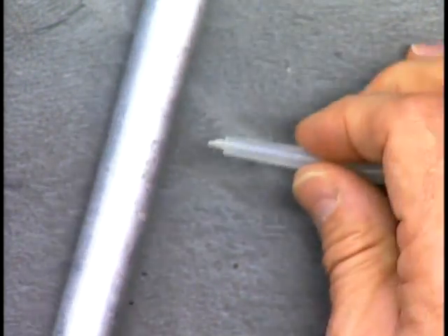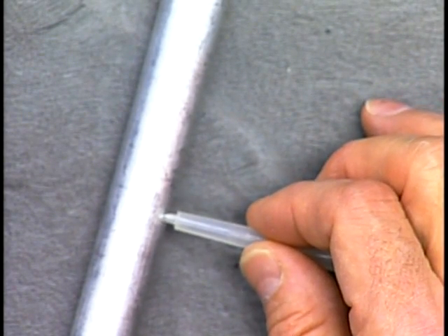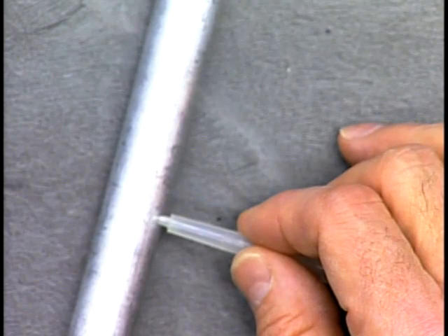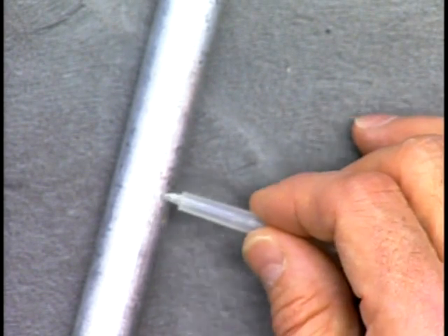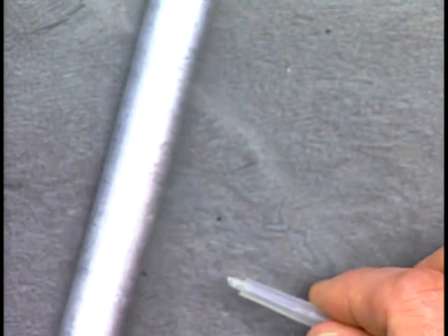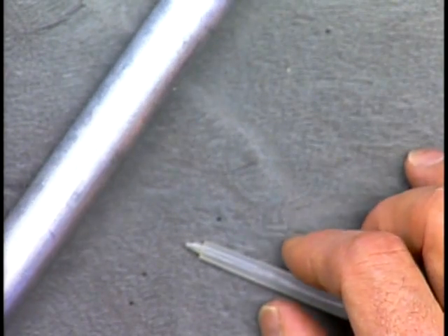And in a more extreme case, which I'll get to later, if I'm coming in here with some sort of a point source, let's say heating it or applying a force here, there's nothing happening out here. It's all happening right here. And the net shape that I get has a lot more to do with how I move that interaction point, otherwise known as a tool, than it does with the tool shape. Tool shape is important, but it's of secondary importance. Okay?